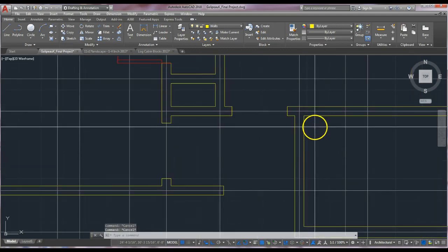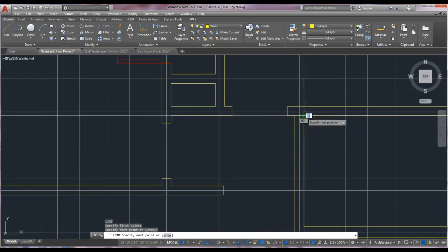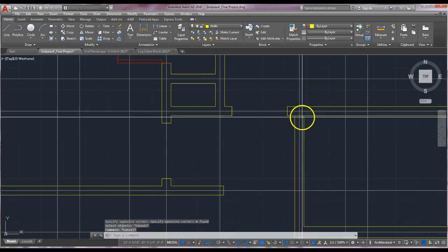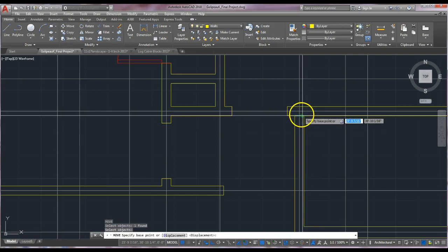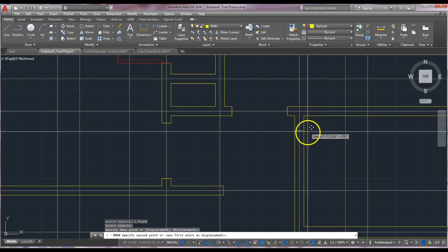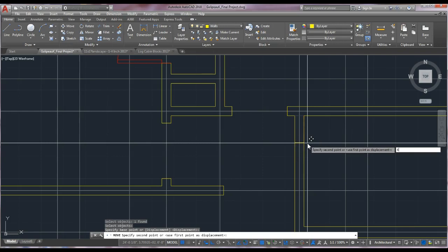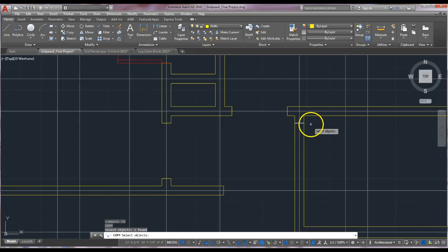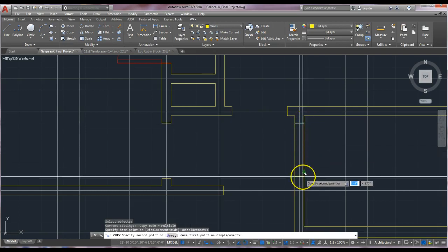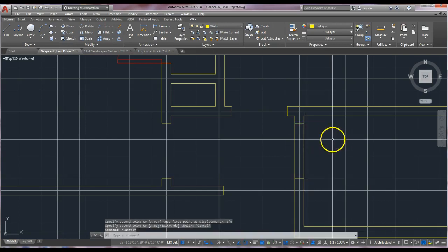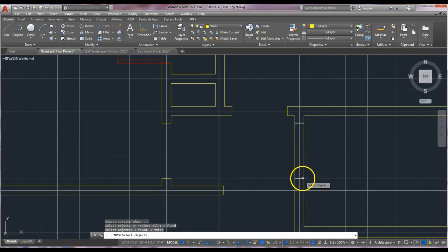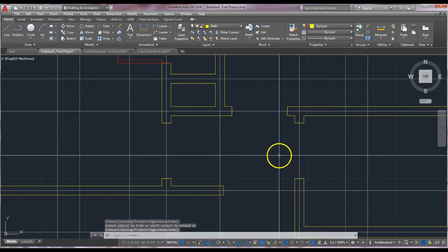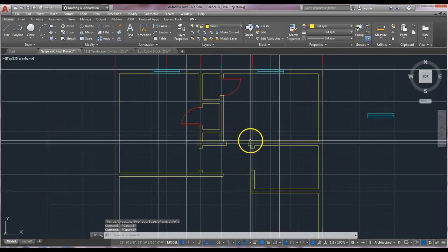So we'll do the same process. Select the line tool, line command, draw our line, move our line in 4 inches. Sorry, move command, select the base point, drag our cursor in the direction we want to go, 4 inches, enter, and then copy, select that line, endpoint, drag our cursor in the correct direction, 2'6", enter, trim. So now our door opening is ready for our door.